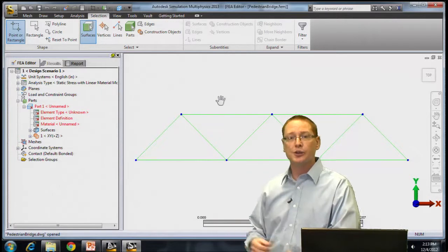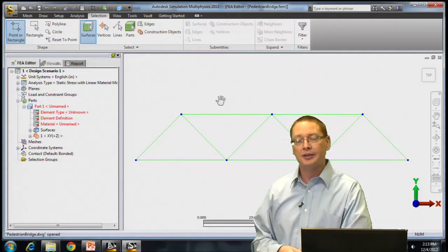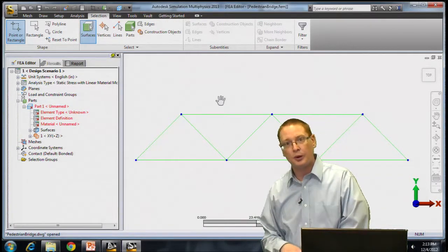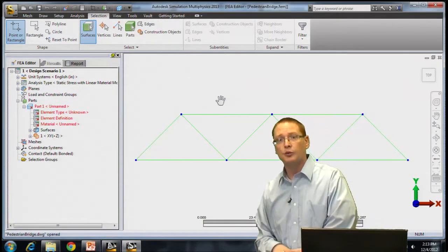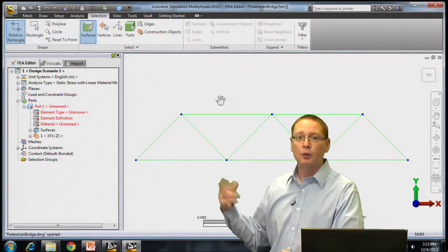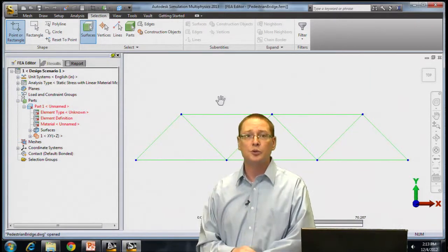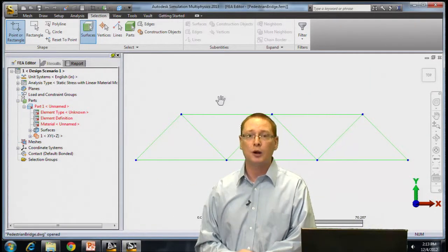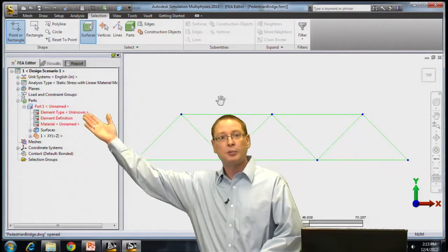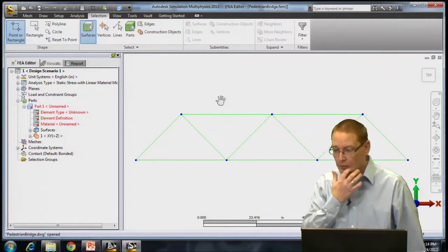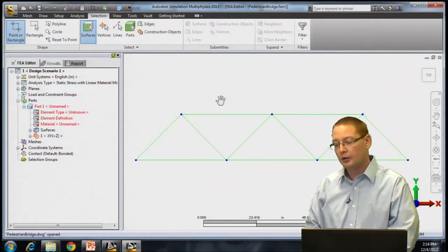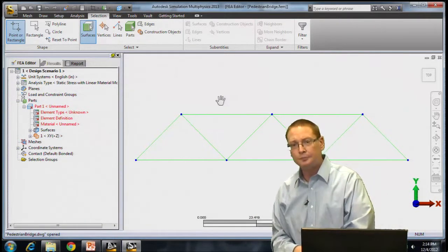Likewise, in simulation, there is a way to select those lines and edit them. You can change them to a different part number, surface number, or layer number. I can show you that. In fact, we will do that for this model. But what I wanted to do was to show you that if we put it on layer number 1 within AutoCAD, it ends up being part number 1 here within the simulation environment. And that is, in fact, what we have.